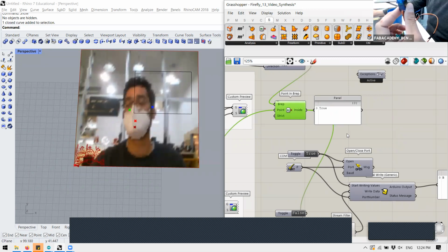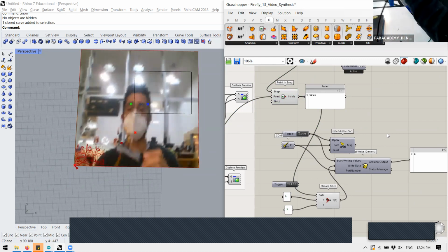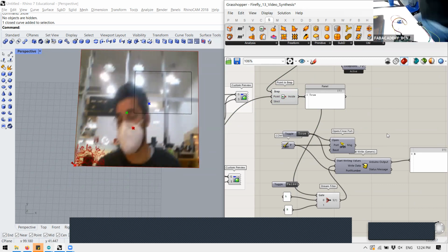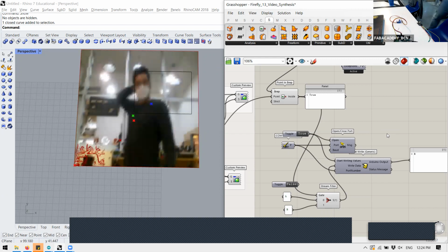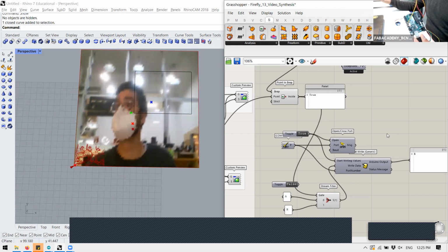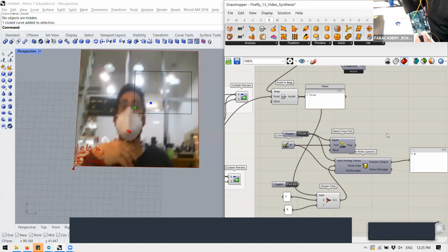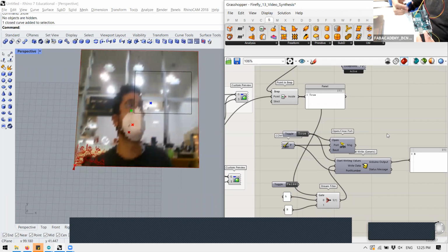With a true or false, what can we do? What is the hardware side of the actuation? What do we have on this other side? We have an Arduino Uno. It could be an Arduino Uno, but could be any kind of microcontroller that has serial connection, because what we are talking about is basically communication through the USB. Could be an ATtiny with an FTDI, could be your ESP32 with an FTDI connector or an ESP commercial board. But basically what we are doing is talking through serial to the Arduino. It's serial communication.